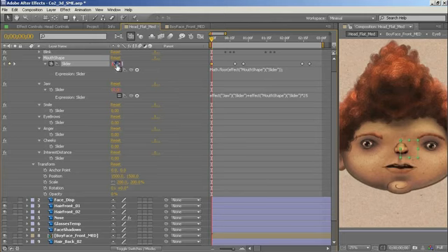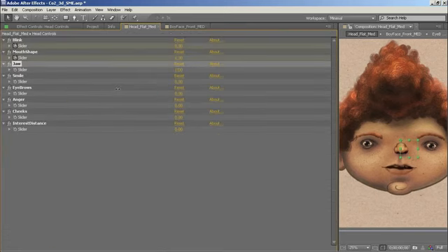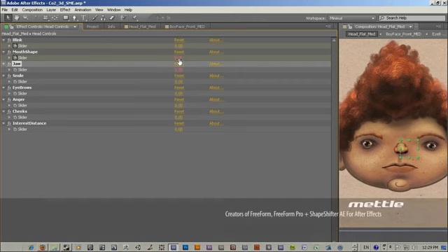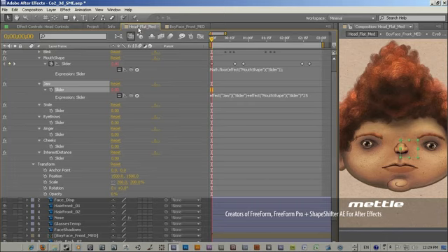I also wanted to have it so the mouth shape influenced the jaw as it does. So I've called up effect jaw slider plus the mouth shape, and I've multiplied that value by 25 in order to make the jaw respond to the mouth opening. On top of that, I wanted to be able to manipulate the jaw further so that if the kid's breathing with his mouth open, or for instance his mouth is closed but maybe he's grinding his teeth or he's setting his jaw or anything like that, I still have mobility there. I did want an independent relationship from the jaw to the mouth.